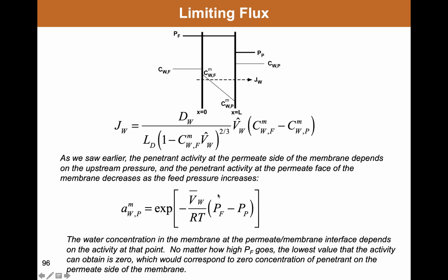Now there's a practical limit to this. You can see that as the feed pressure goes up to really high values, the thermodynamic activity of penetrant on the permeate side of the membrane asymptotically approaches zero. So as P feed goes to infinity, the right-hand side of this equation goes to zero.